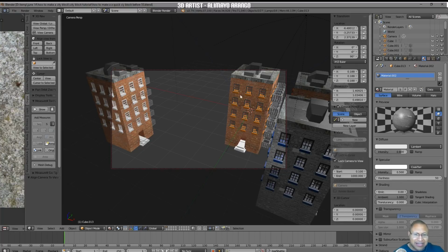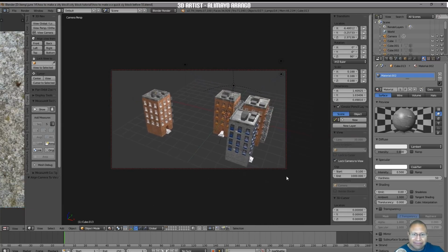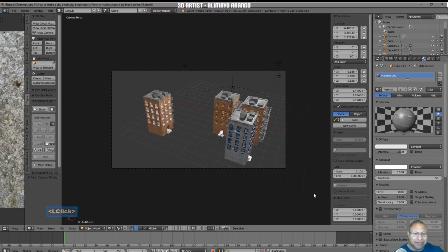And what this does is this allows me to control the camera view just like I was controlling the regular Blender view. So I'm going to hold Control and the middle mouse button to zoom back. And basically what I'm doing is I'm lining up what I want to have in the view of the camera. So I want the things I build to look good, what we see here in the camera. So now I'm going to unclick lock camera to view.